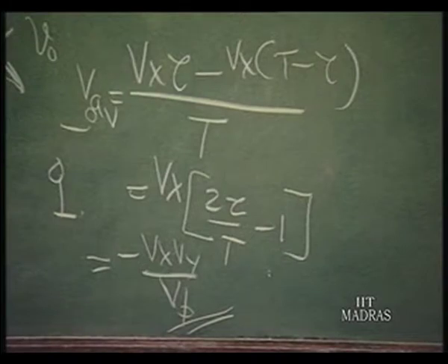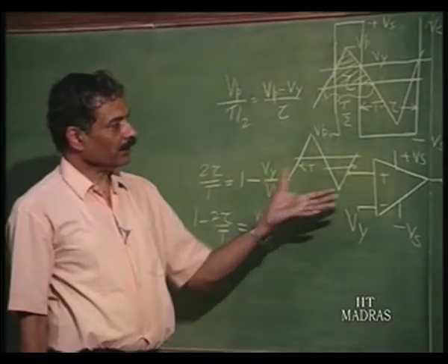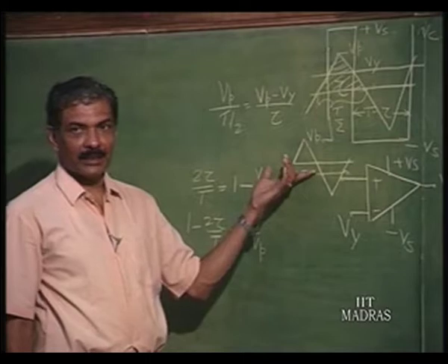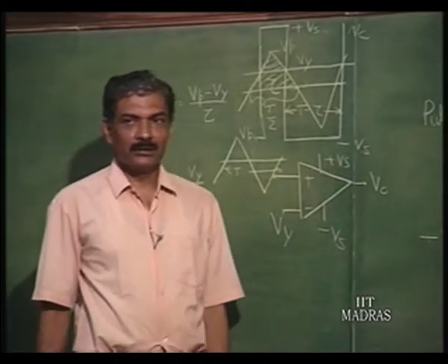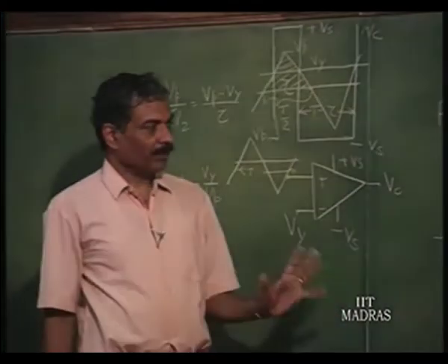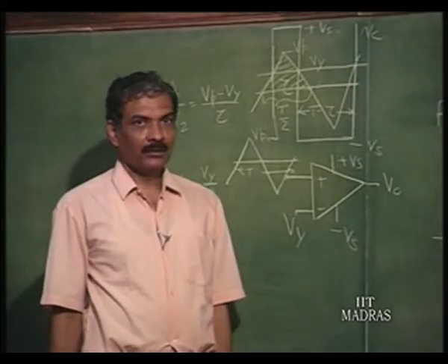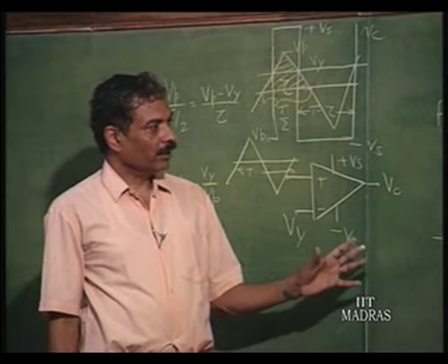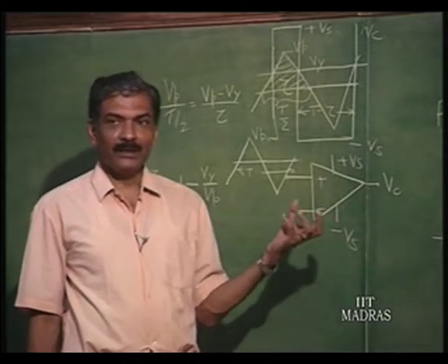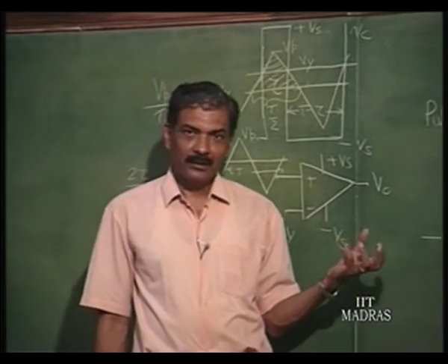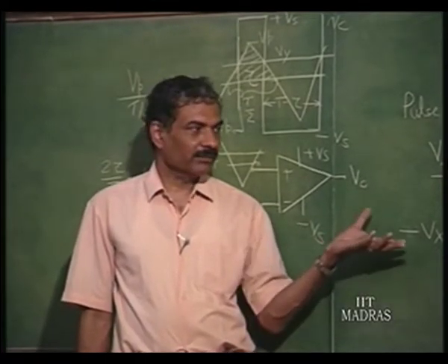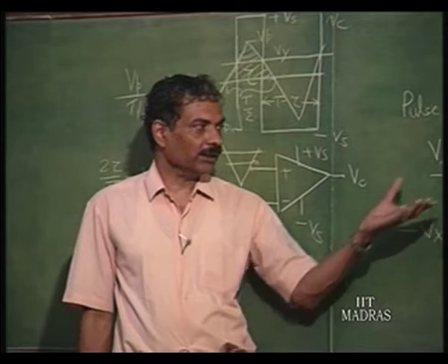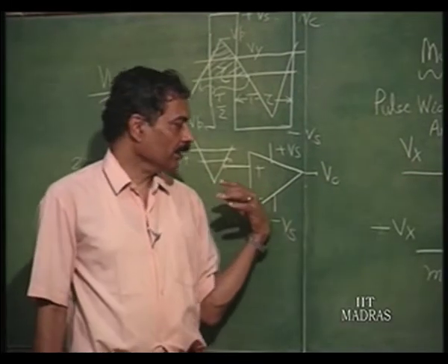So, this basic principle uses a comparator, a triangular waveform generator, and Vx and Vy and switches. So, you get exact multiplication without the property of the active device being used. So, this is very accurate because it uses only switches and comparators.